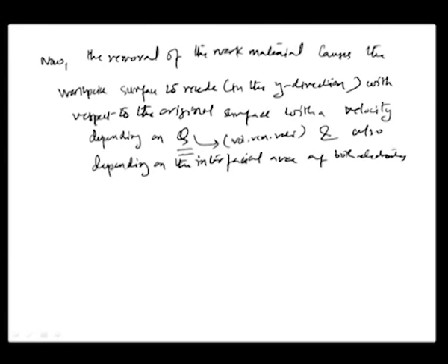Obviously, if we consider a one dimensional motion, the volume removal rate per unit area of interface of the electrode would mean nothing but the velocity of recession of the surface because of the dissolution.